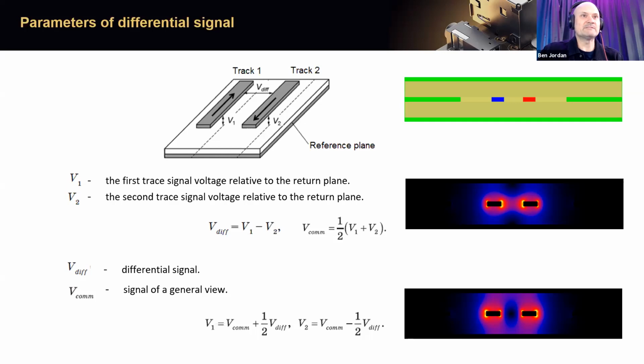And I've added some images on the right there, which I made using a really cool free open source calculator called ATLC2. If you want to download that and have a look at it, it gives you a visualization of a static field on a transmission line.